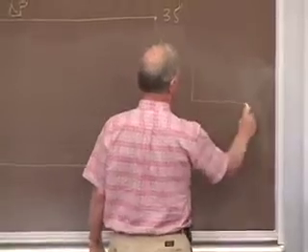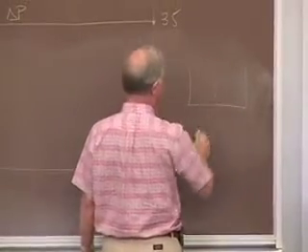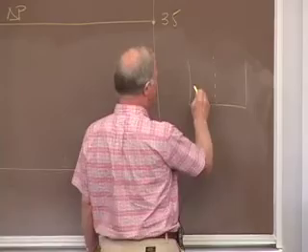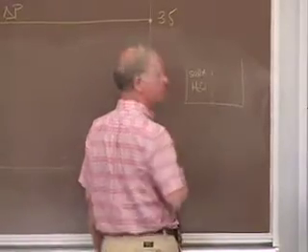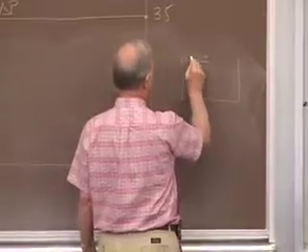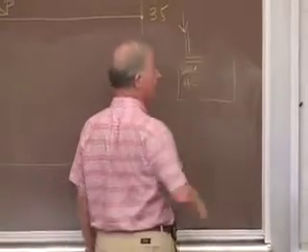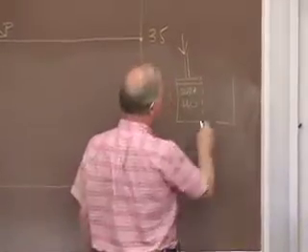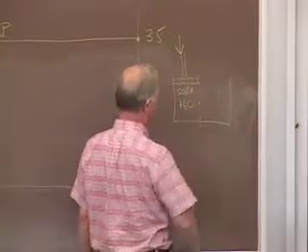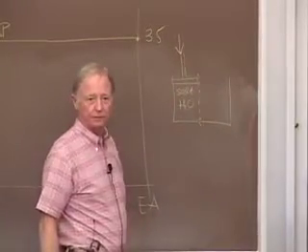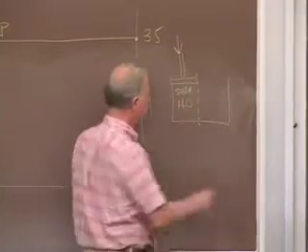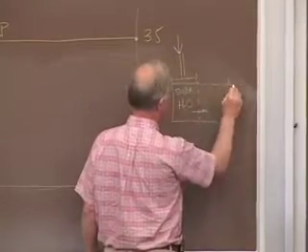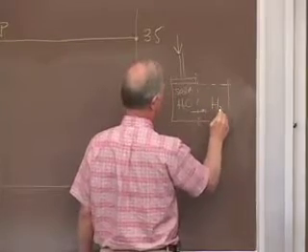Well, you take a pot, you put a semi-permeable membrane in this pot, and you put salt water on this side. You put a big piston here and you press on it. And this membrane is permeable to water but not to salt. If I press on it hard enough, what happens? It pushes the water over here, and you get fresh water.